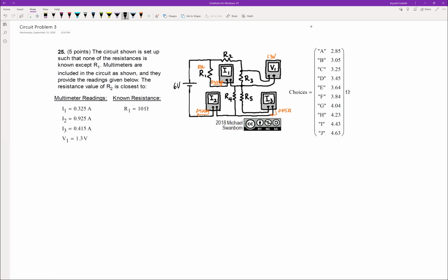The next thing I would do is identify the nodes. Identifying the nodes will help you understand what's in series and what's in parallel. In order to identify the node, you'll highlight the connected space within the circuit without crossing any circuit components. With the first node starting at the power source, we'll label the first node 1. Then we'll continue and identify node 2.